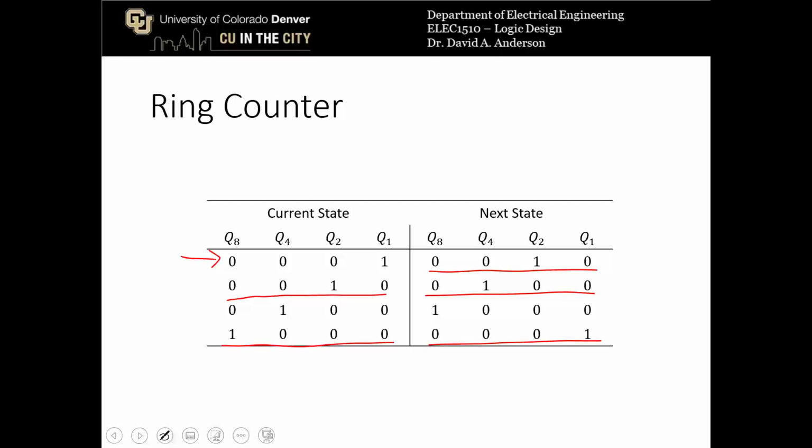So again, you could go through and assign T flip-flop inputs or JK flip-flop inputs, or even D flip-flop inputs, and construct the counter that way. One caveat to this is that in Quartus, the flip-flops always start in a state of 0, 0, 0, 0, which means that you would be governed by the don't care conditions, most likely.